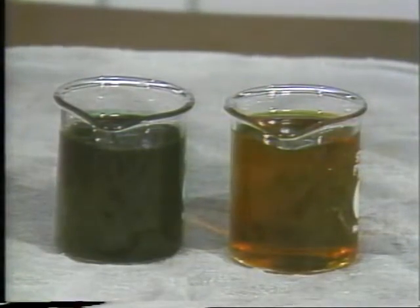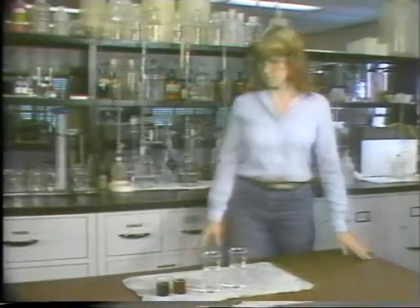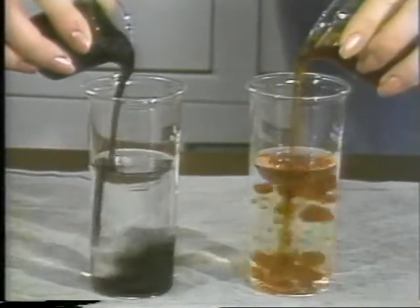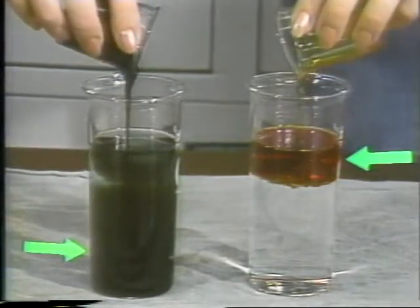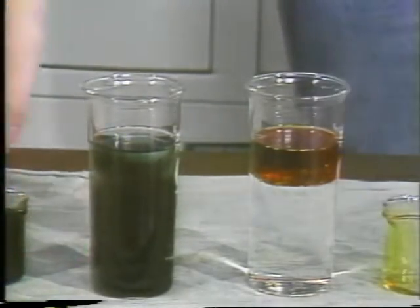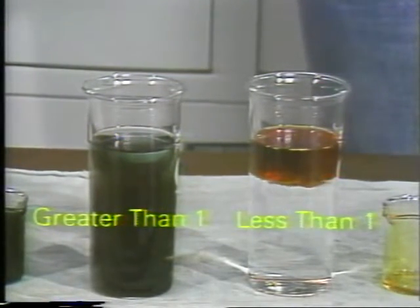Let's go into a lab where we can illustrate this point with these two different lubricants used in a plant. In most cases, lubricants are less dense than water and will float, but this isn't always the case. Watch what happens when we pour each lubricant into a container of water. The first lubricant sinks to the bottom, while the second lubricant floats on the surface of the water. Without doing any calculations, we immediately know that the first lubricant has a specific gravity greater than 1, and the second lubricant has a specific gravity less than 1.